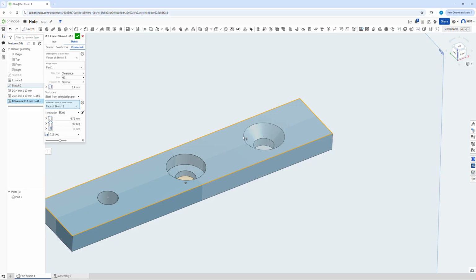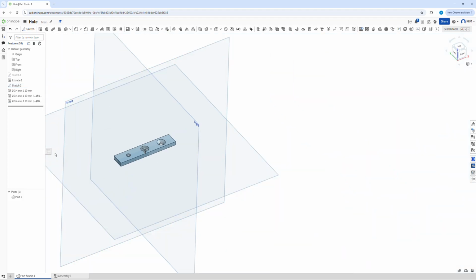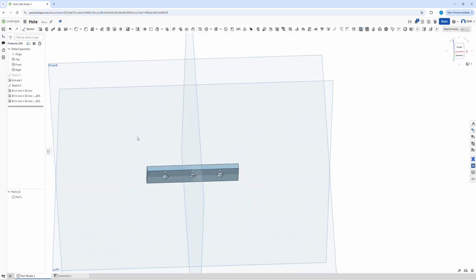So when you drive the drill and the screw in, it basically pushes into the wood to make it flush. You can obviously use a countersink tool to make this so you don't split the wood if you're doing really delicate things. Again, you can change all of this if you so wish, but that is a basic setup for different holes depending on what you are going to be doing.